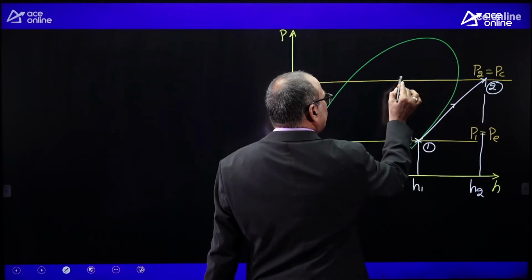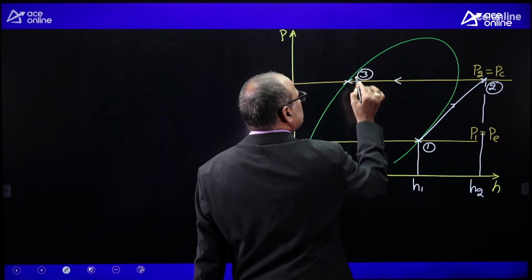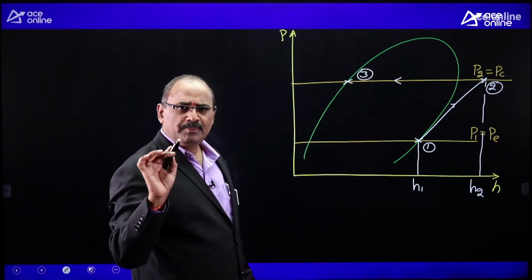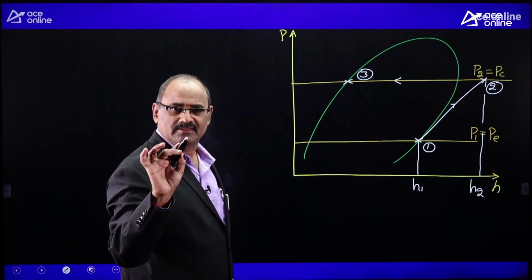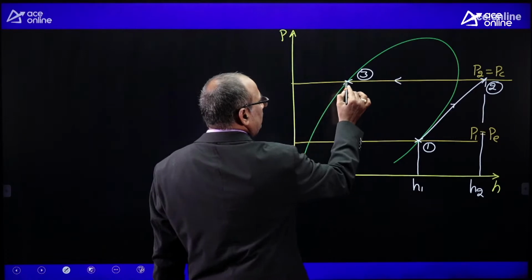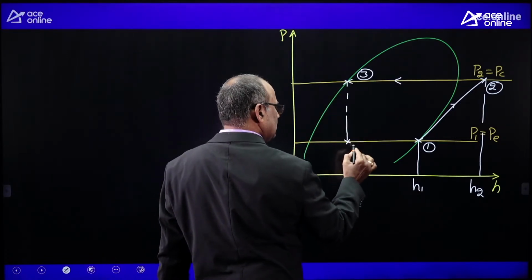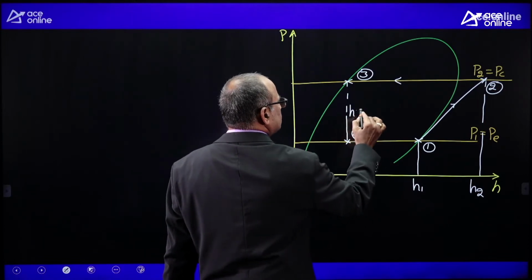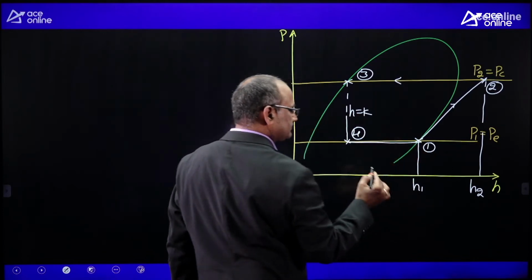That superheated refrigerant is becoming saturated liquid refrigerant for the simple cycle. That means I am going to project the p-h diagram without considering the subcooling effect first. Without the subcooling effect, 3 to 4 is the irreversible adiabatic process, that is the throttling process, where enthalpy remains constant. And 4 to 1 is the evaporation process.